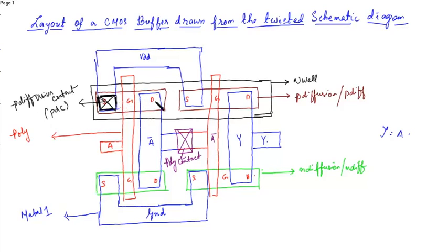Since there are two PMOS and we have two terminals in each PMOS, in total we have to place 4 P diffusion contacts because there are 4 metal junctions in the P diffusion layer. So over here, in the portion where you want to connect the metal with the P diffusion layer, you have to place this contact. Similarly over here.